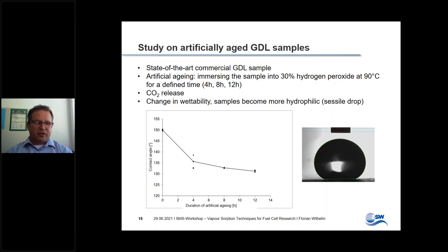Just as background information, this contact angle you see here with the sessile drop method has a strong impact of the surface geometry. So the so-called lotus effect, describing the phenomenon that you get much higher contact angles than for pure flat material once you measure on corrugated surfaces, also comes into play here. Pure PTFE with a flat surface would have around 113 degrees of contact angle.